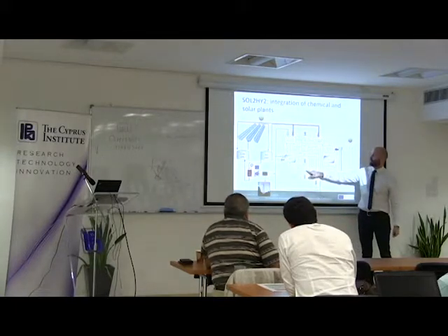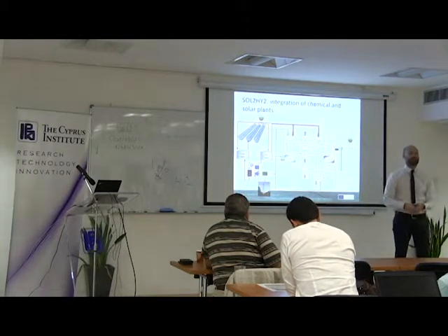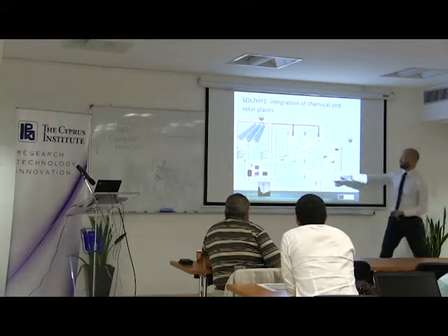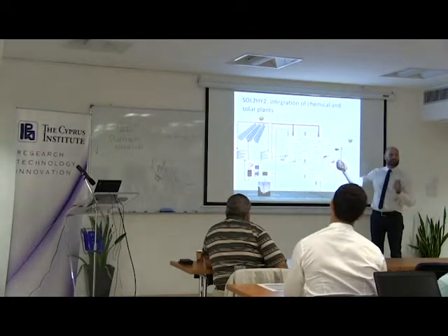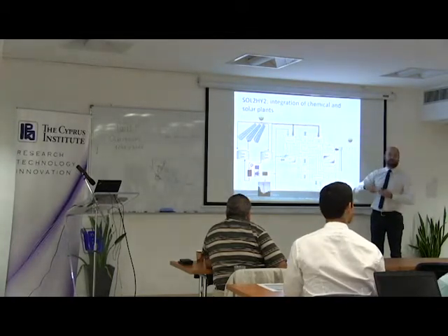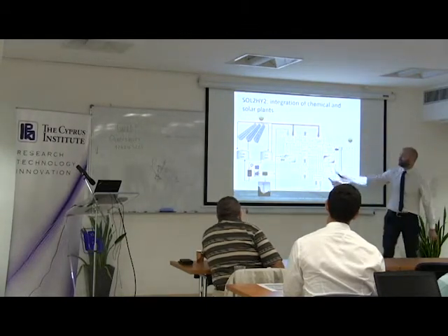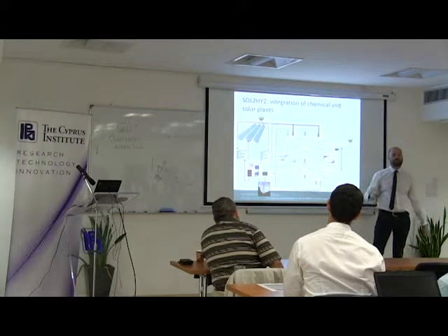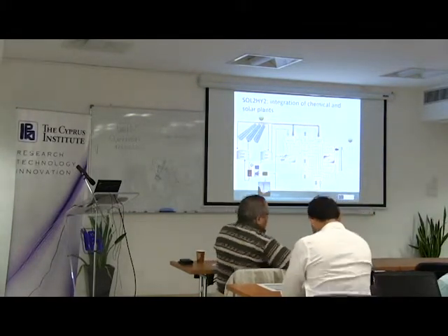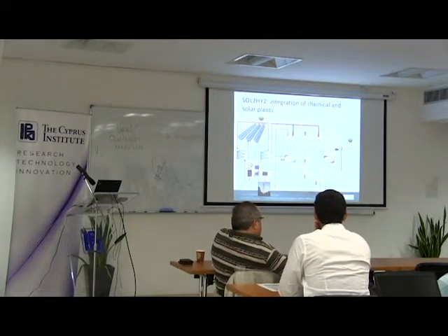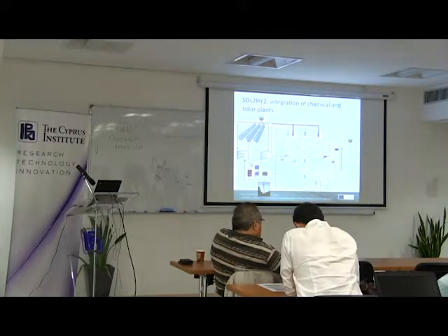So we store sulfur dioxide and sulfuric acid, but this is also a way of storing energy. Basically, this is a chemical storage, because when we have sun to power the high temperature part, we do the cracking of the sulfuric acid and we store liquid SO2, which is a feedstock for the second part of the process. So we're turning what is a limitation, a drawback, into an opportunity, because this plant has several opportunities of flexibility during the year.